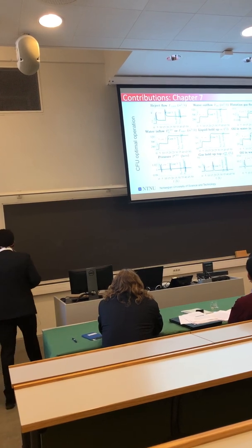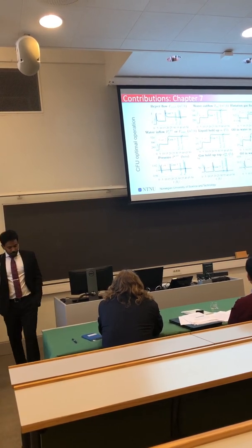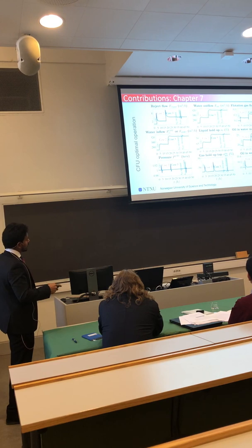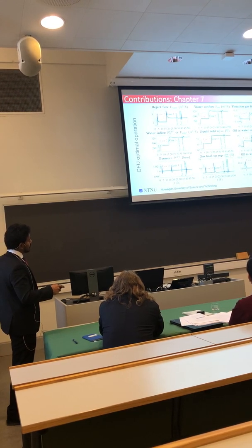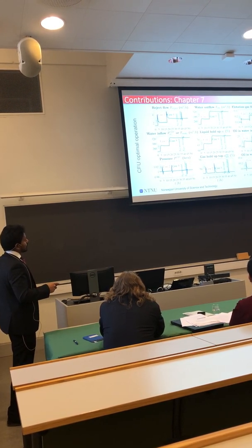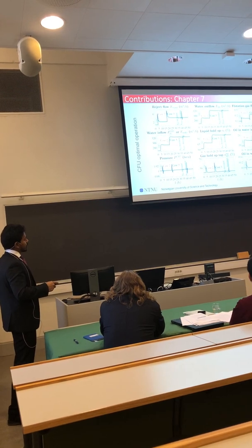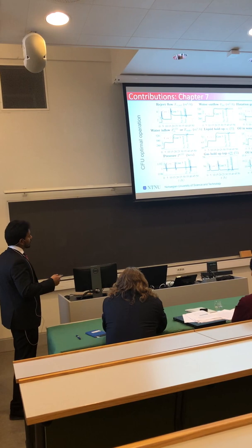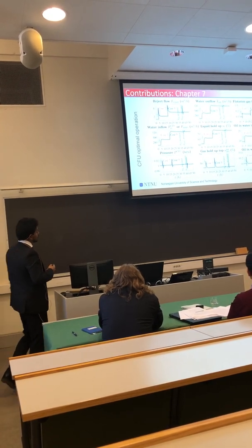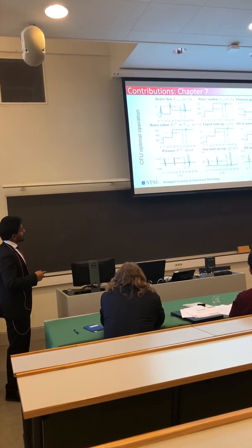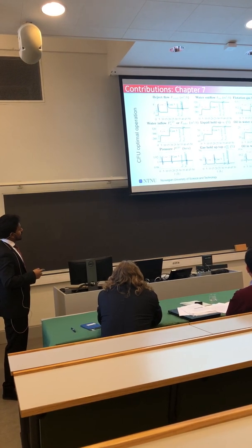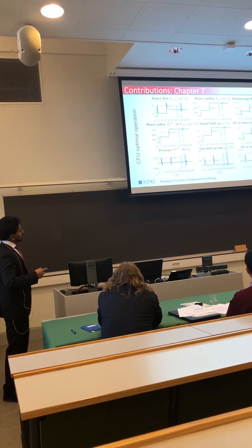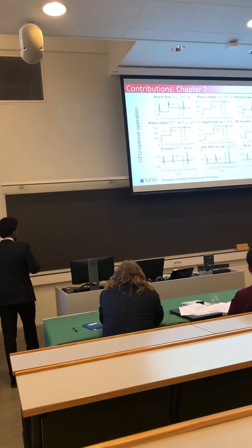And the final stage is the CFU, where the most important thing is that we are able to maintain this 10 ppm limit in all cases for all disturbances. And the gas holdup is maintained at 55% for all cases, and the pressure is maintained at 1 bar. So this is a fairly okay control structure to control this process, and it is able to handle all the disturbances that are coming from the upstream using these 3 different control inputs.